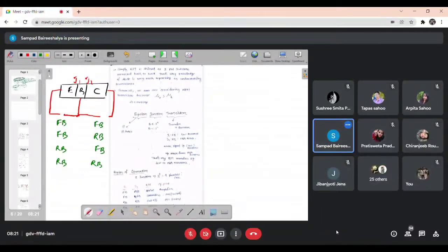Remember, out of all such cases, when the input junction is forward bias and the output junction is reverse bias, this is called the amplification case. इधर तुम्हारा सिग्नल एम्पलीफाई होता है, and in this situation it works like an amplifier.